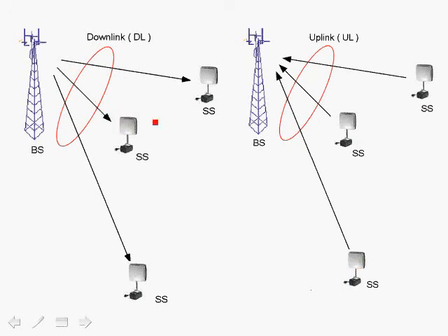Let's review the scenarios for multi-user interference, that is, interference from other users into the carriers of other users in OFDMA. One of the issues that we've talked about, of course, is carrier offset. We've also talked about timing synchronization requirements to align the reception of all the symbols from the multiple subscribers at the base station.